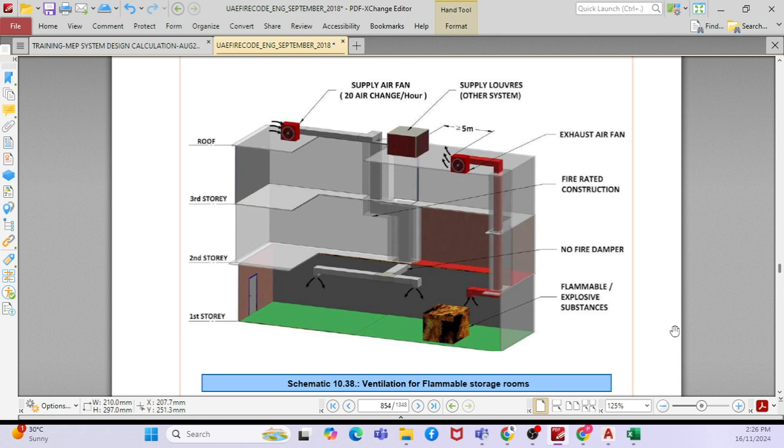For the intake, it can be from an intermediate plant room, taking the intake from an intermediate floor. Can I keep the fan within the room and duct it directly outside with a louver, and then take the fresh air from there, instead of taking the duct all the way to the top? Directly outside is not allowed unless it is an intermediate plant room.